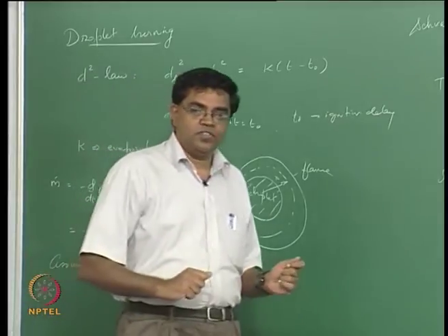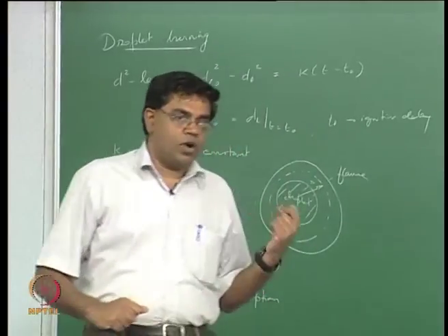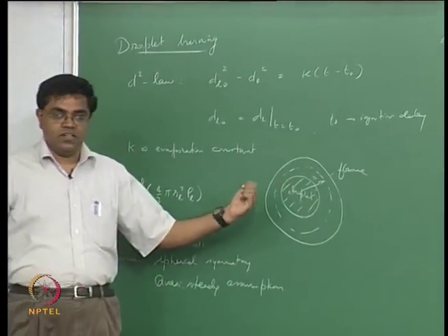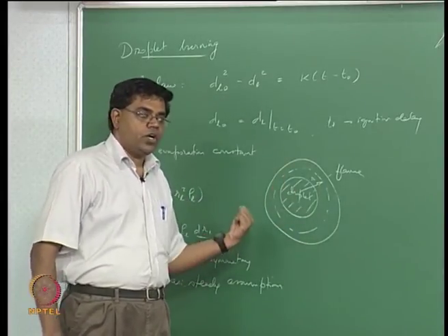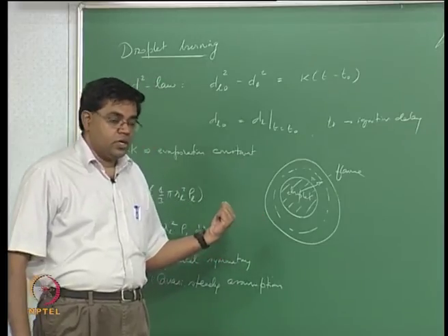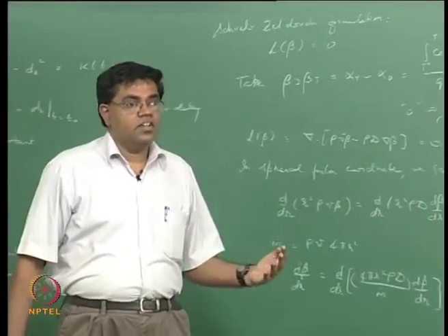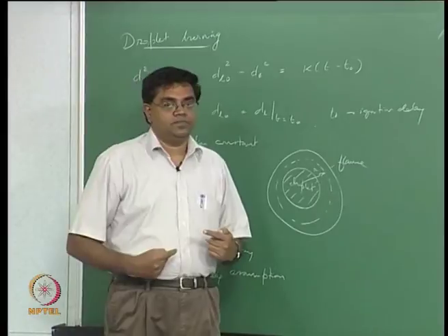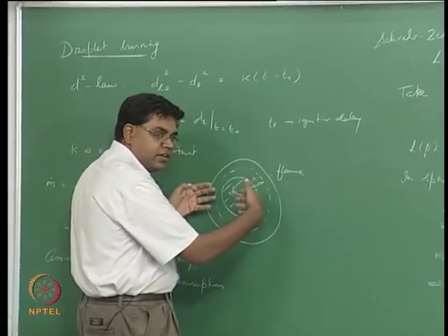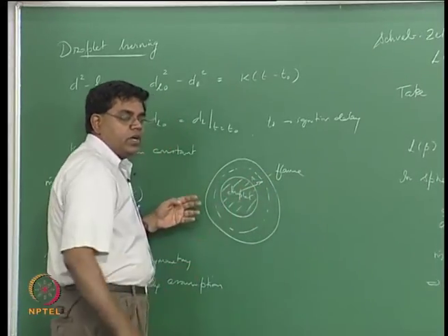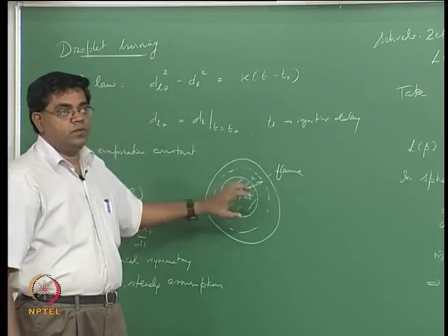Now the difference between these two situations of aluminum combustion and methanol combustion is, in one case the product liquid that is condensed is immiscible with the parent molten aluminum fuel droplet, whereas in the case of methanol the product water that has condensed is miscible with the reactant fuel in liquid form. So as the water comes back in, it starts mixing with the liquid and effectively dilutes the fuel.